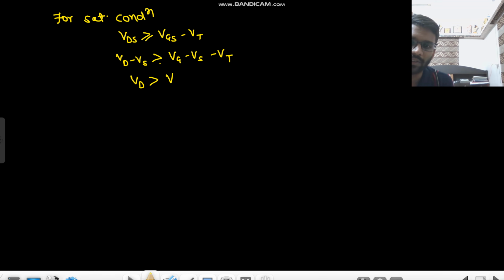Why so? For saturation, what is the condition? VDS is greater than VGS minus VT. We can also write it as VD minus VS greater than VG minus VS minus VT. Since VDS equals VD minus VS, the VS cancels, so VD should be greater than VG minus VT.